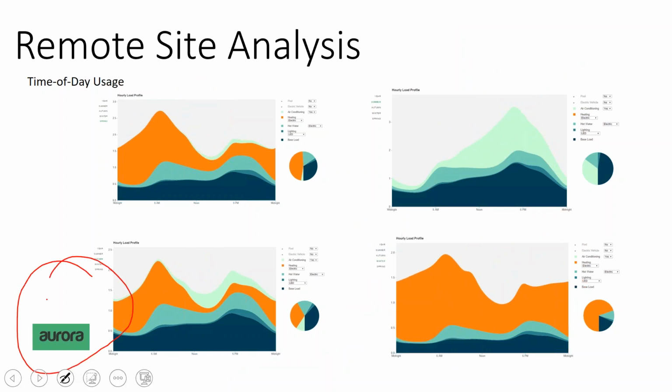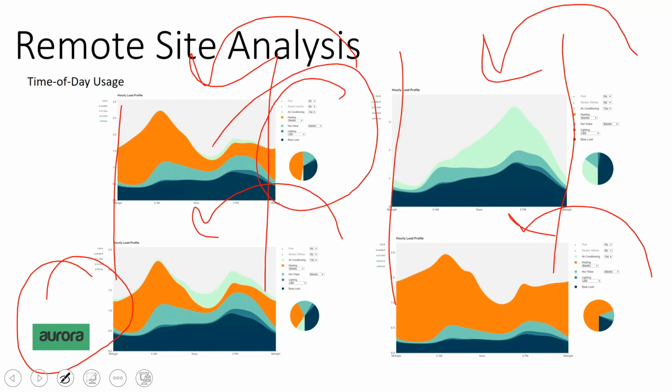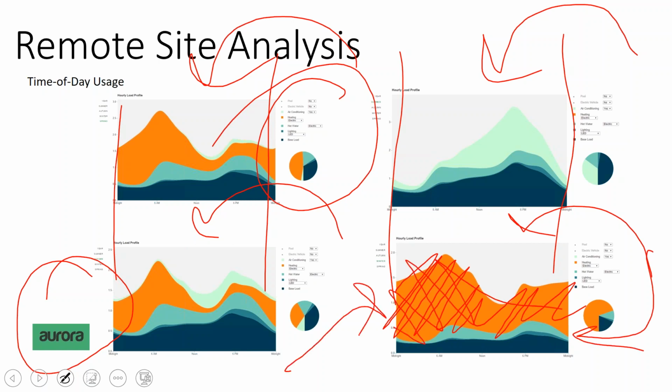So one approach that Aurora Solar uses is a pretty good one. Some utilities will do this too, is they'll take your month-to-month electric bill and then break it into a daily average, like what we've talked about previously. So you take how much energy you use on an average day, and then you fill out a survey of what appliances you're using, whether it's a tank water heater or a tankless water heater, electric heat, gas heat. That's going to make a big difference. If you're on wood burning heat, you could eliminate your electric heater, and then your wintertime electric bill is really low. If you use an electric heater, then your wintertime electric bill is going to be really high. And so just from doing a survey of what appliances you're using and what region your building is located in, they've already taken building load profiles for your region, and based off what appliances you have, they will estimate the load profile for you.